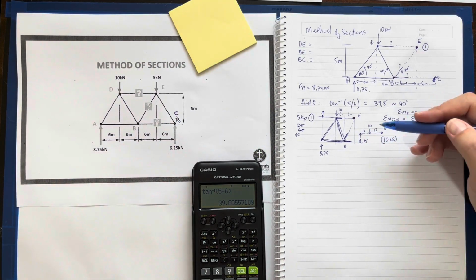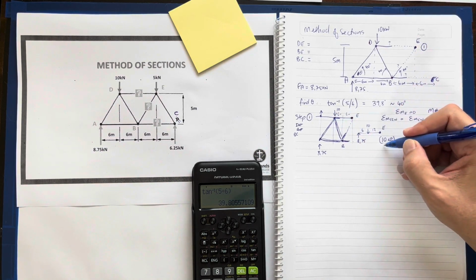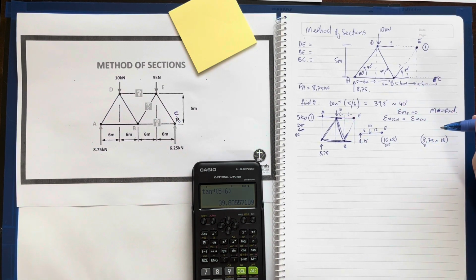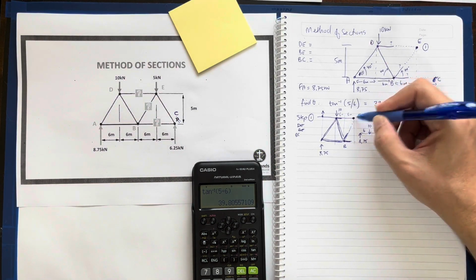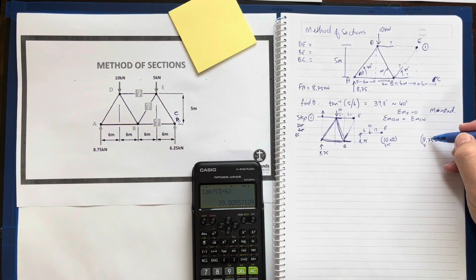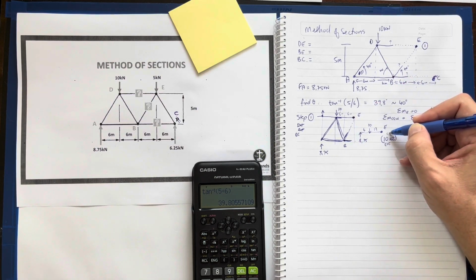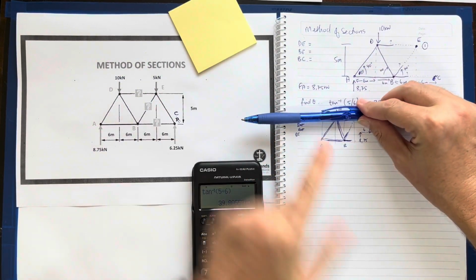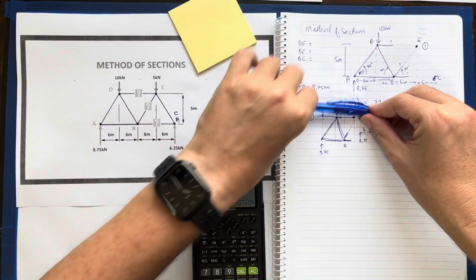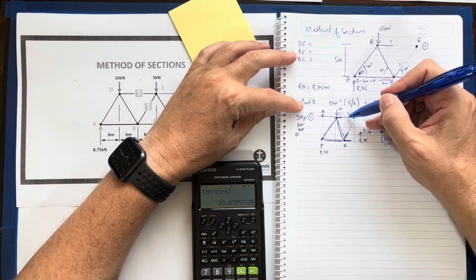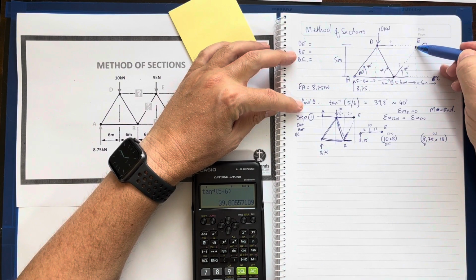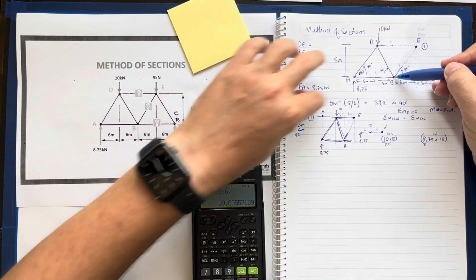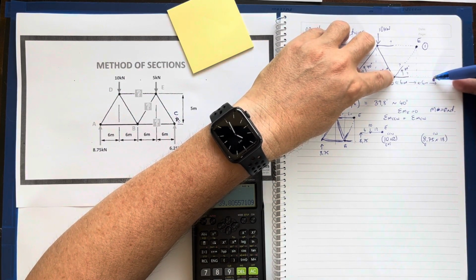Now this is where the trick comes in. So I have both my external forces. This is an external force that's causing a rotation moment around point E, and it's counterclockwise, and this is causing a clockwise motion, wanting it to spin in this direction. But I'm not looking at DE because it's touching that point. I'm not looking at that, but I still have BC that needs to be solved.